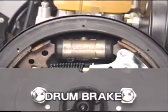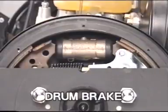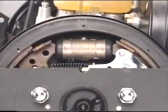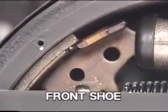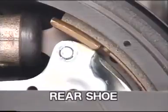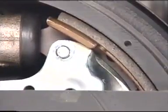The drum brakes use friction generated by rubbing the drums against the lining to stop the vehicle. Opposite forces are applied to the front and rear shoe. The trailing shoe tries to push against the force, while the leading shoe is pulled into the revolution and produces a larger brake force.